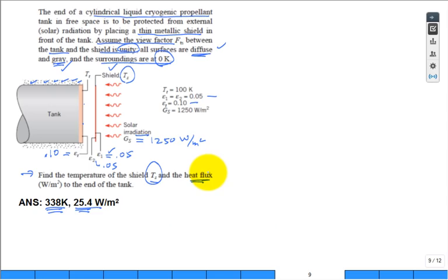All right, so what I was looking to do is to have you set up and put a node, and then put the EB of the tank surface corresponding to this tank surface there. Whenever you have a surface like that, you have the radiosity node for that tank surface. And this resistor right there is 1 minus epsilon over epsilon A. Let me fill that in a minute.